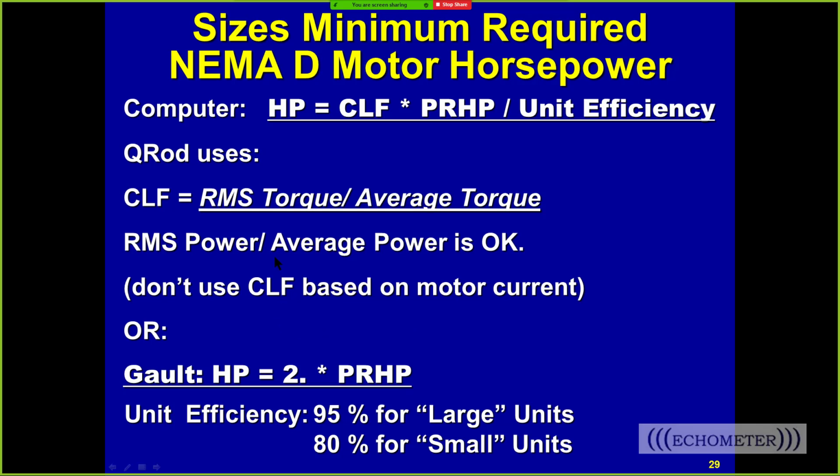Now, Bob Galt said this is a bunch of hooey. Bob Galt was a famous pumping unit design engineer, and he said just take the polished rod horsepower times 2 and use the next larger size motor, and that's going to be good enough, as long as the fluid level is down at the pump. That will be correct.